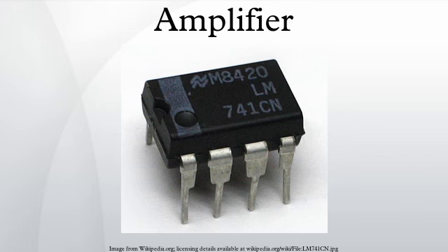This category subdivides into small signal amplification, and power amps that are optimized for driving speakers, sometimes with multiple amps grouped together as separate or bridgeable channels to accommodate different audio reproduction requirements. Frequently used terms within audio amplifiers include preamplifier, which may include a phono preamp with RIAA equalization, or tape head preamps with CCIR equalization filters. They may include filters or tone control circuitry. Power amplifier, headphone amplifiers, and public address amplifiers.